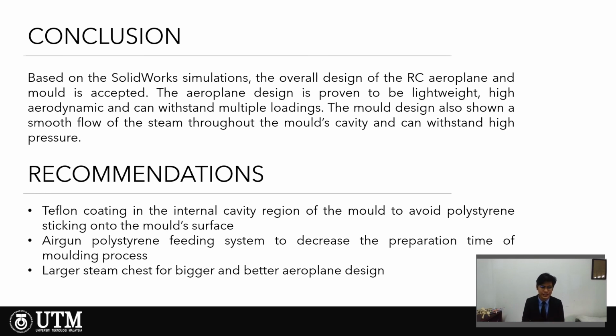As my recommendation, I suggest putting a Teflon coating in the internal cavity region of the mold to avoid polystyrene sticking onto the mold surface, an air-gun polystyrene feeding system to decrease the preparation time of the molding process, and a larger steam chest for a bigger and better aeroplane design.